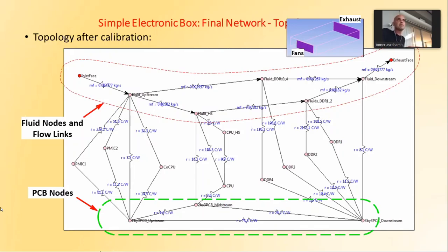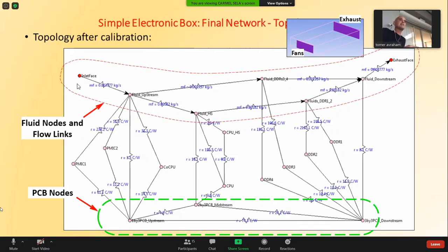And then there's no problem. I mean, you can do that for a few sections, another section, another section, another section. Yeah, it takes a lot of work to do the ROM itself. But then after that, the ROM takes time. It's a big set of, let's say, 64 CFD runs you have to solve. But then afterwards, you can use that as a real-time tool for solving problems in real time in the range of validity.